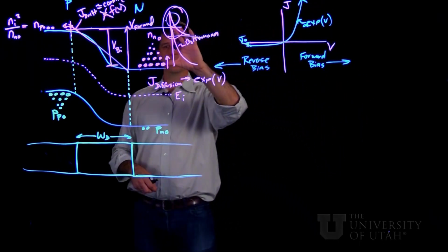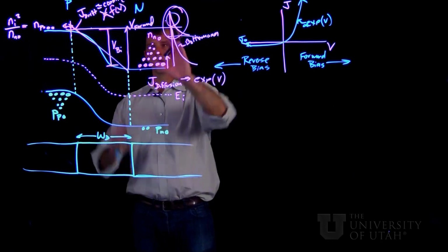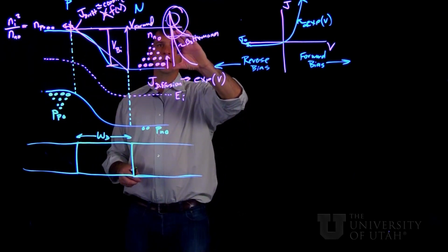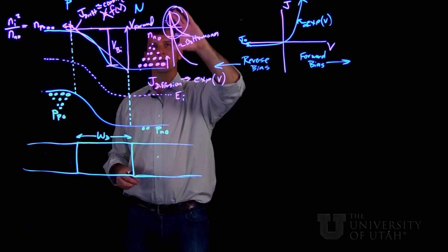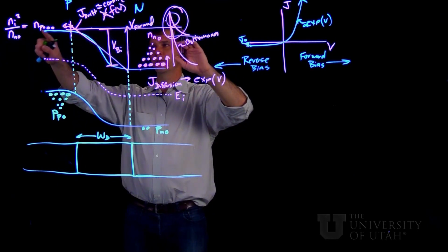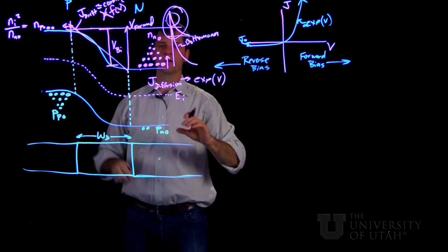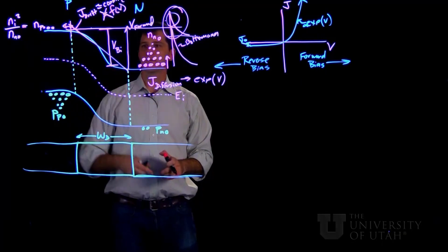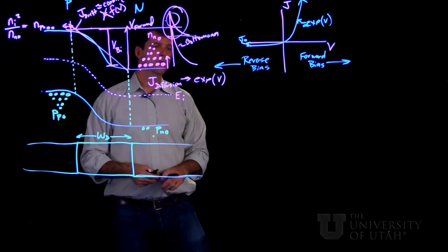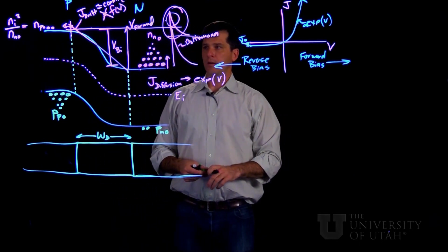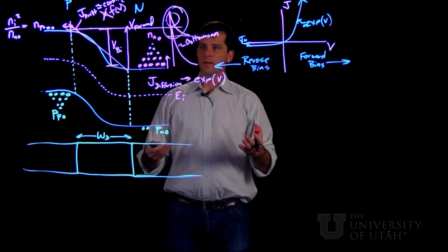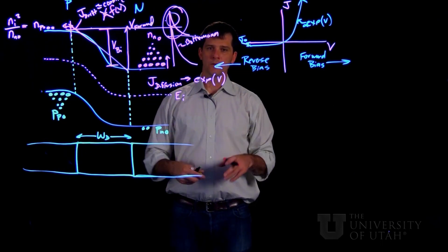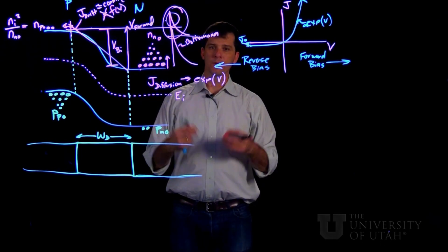And it's because of the diffusion current across the junction and enabling a larger and larger fraction to be at a high enough energy that they can diffuse across by the application of that forward bias. The drift component stays rather constant, and now we'll look into how we can actually calculate these currents as a function of properties of the junction.